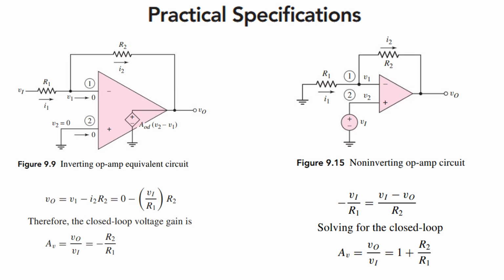So how can you calculate the output voltage or the gain? Very simple, since the input impedance between the minus and plus terminals is infinity, as we just discussed in the ideal characteristics. If the resistance between the inverting and non-inverting terminals is infinity, then no current will flow.